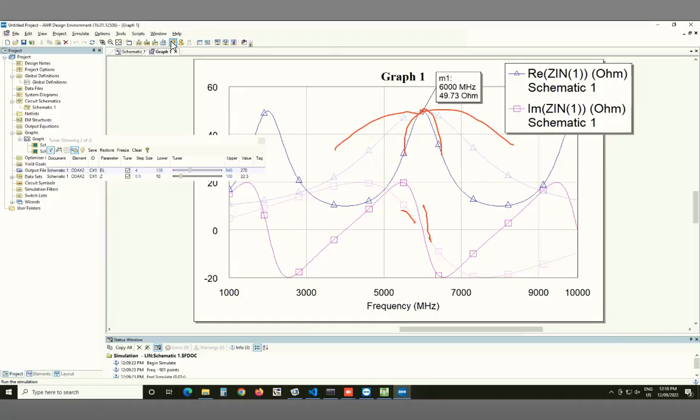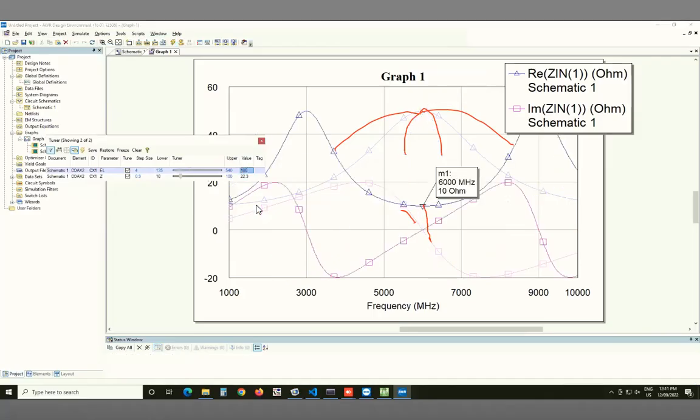There are, of course, many other ways of doing this, but I just wanted to point out that it's not equivalent in all senses. This idea is simple, but I want to emphasize again and again that whenever we work with transmission line sections and talk about impedance matching, the exact matching condition is always at one frequency. How things change from there depends on various other factors. Is it lambda by 4? Is it 3 lambda by 4? This also happens for the lambda by 2 case which we just saw. So here you see this opposite sign.